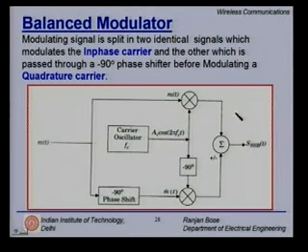You do not have to worry about any band pass filters or how sharp the cutoffs are. So, both the methods, either using a band pass filter or a balanced modulator, have their pros and cons. Here the errors will creep in if the phase shift has a drift.